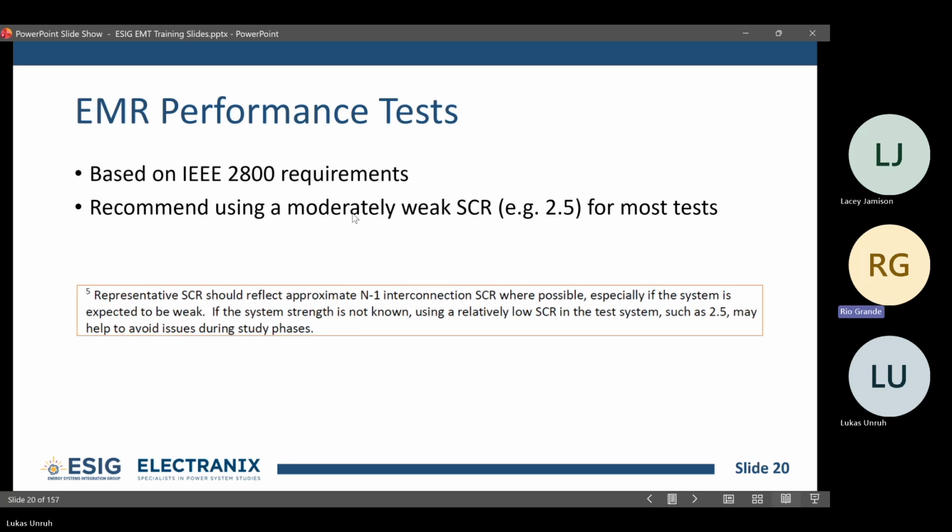What about the X/R ratio? Do you have an X/R of 5 or 6? Is there something behind those numbers, or are they just random? I wouldn't say they're random. If you have a power flow case, you can poke around pretty easily in most systems and get a feel for the X/R ratios at various voltage levels. They'll vary, but at around 138 kV, I would say 5 to 6 is pretty reasonable. As you go up in connection level, you might get some higher numbers. If you go down to 69 kV, you'll get maybe a little bit lower numbers.